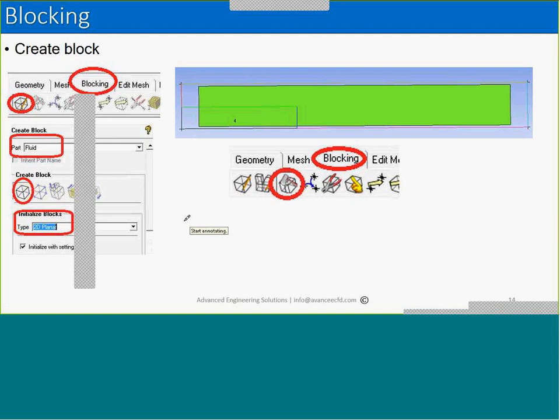So the block shape will always be of the block type, which is cubical. It will have a different mesh shape depending on the geometry we associate the block with. So the block is an intermediate thing which you work on and link with the geometry. Once you link it, you will get a mesh for that geometry.